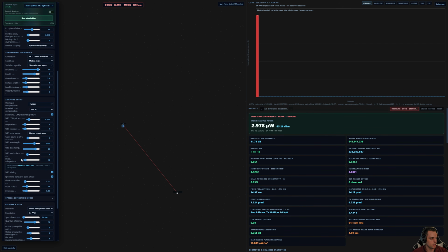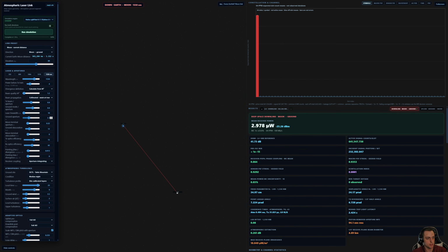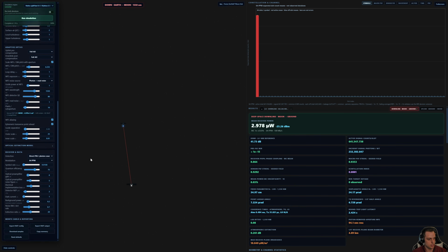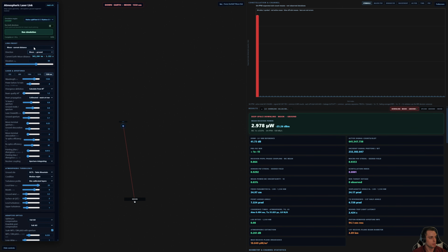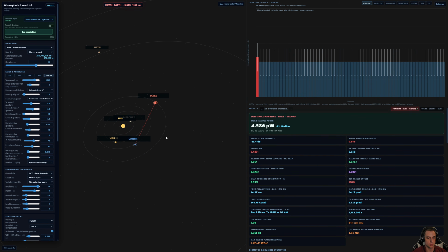And this is based on they use the Hale telescope. It's 5.1 meters. I think we already talked about this. And a 22 centimeter aperture receiver. And so in this case, you can have fairly high data rates out to the moon if you use optical. And this is kind of becoming the replacement for the deep space network, which previously had to use these giant X-band antennas.